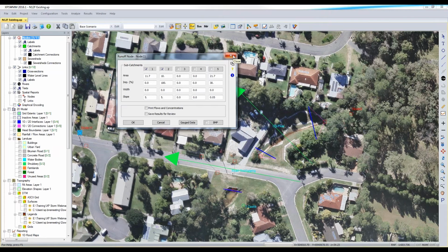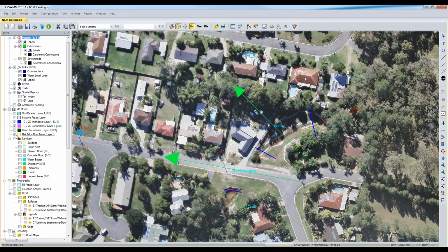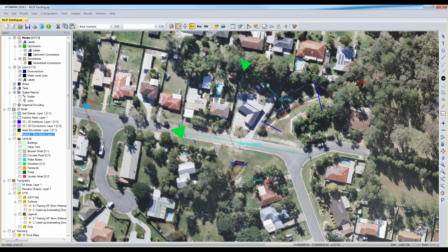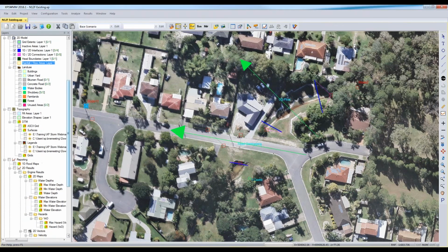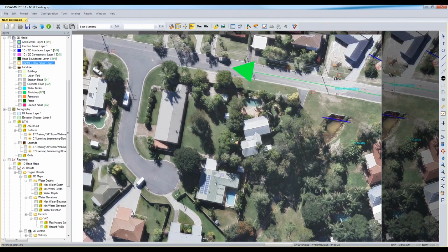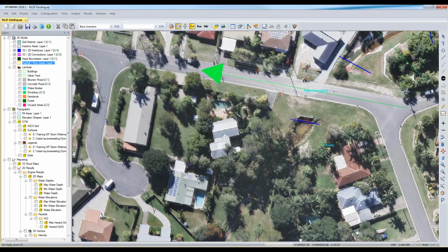For this one, I didn't actually put a rainfall layer on because I was more concerned about the flows coming in and not so much the flows locally. Now, what I'll show now is just for people who are, I see about 50% are not very comfortable with urban modelling. So I was going to use this model just to show you what you want to do if you wanted to model in a 2D network in this area. So I'll just model in some nodes. So your nodes are your manholes and your gully pits, and I can see a gully pit just here and just here, and I know this isn't going to happen, but I'm just going to put an outflow into the channel.